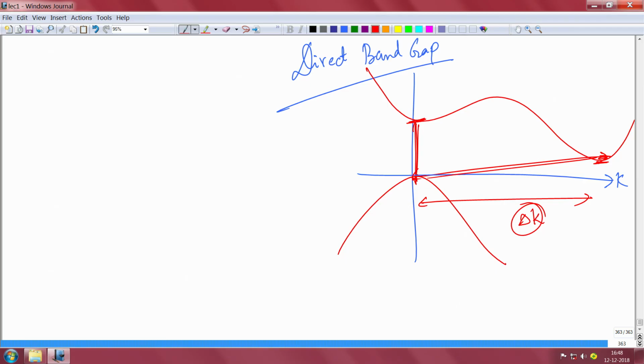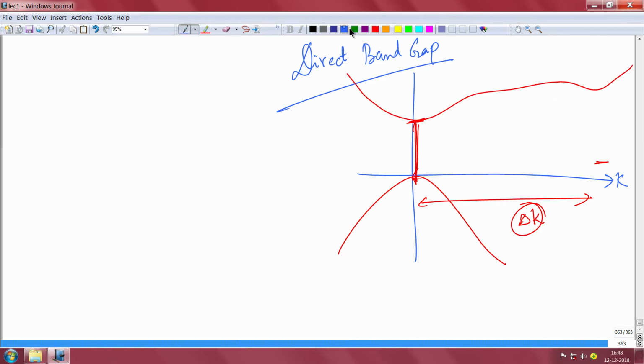Now suppose I talk about a direct bandgap material only, like that. You see there is always a distribution of carriers here. Electrons will occupy the lowest part, holes will occupy the lowest part. The center of the distribution is not exactly at the band edge. So although the band gap is Eg, the light emission wavelength, the energy of the photon, will be slightly more than the band gap, because the electrons are distributed like this and holes are distributed like this.